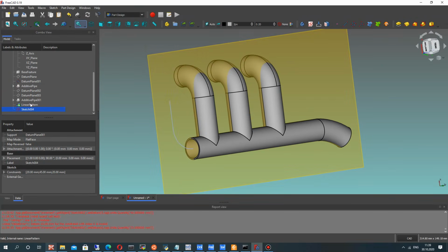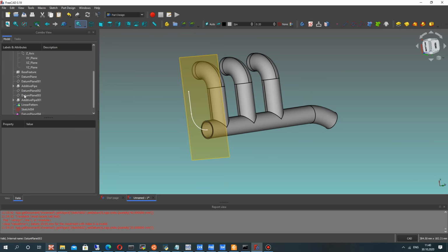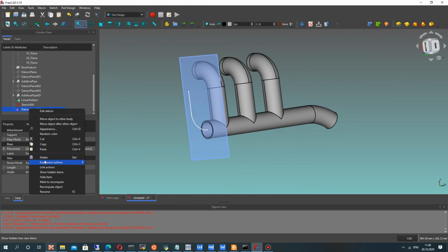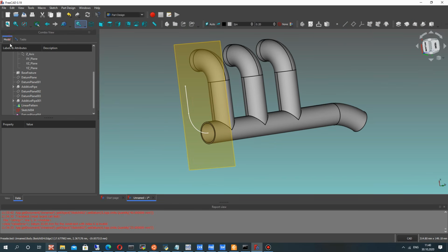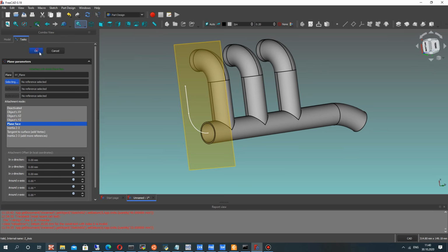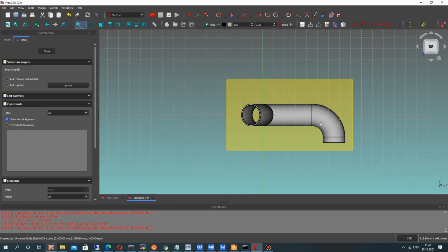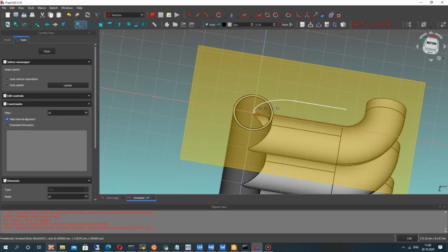And let's hide our datum plane, space bottom, and create one more datum plane. I want to check, maybe we have it here, but we don't, and let's create one more datum plane for the XY plane without changing of position. Okay, and for this datum plane, let's create the sketch with 2 circles,